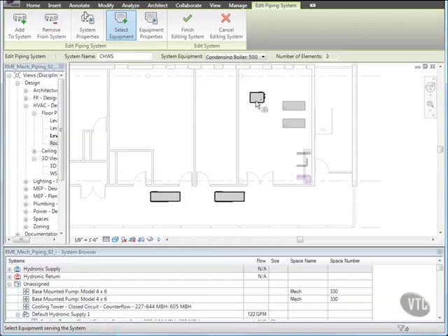You're selecting the boiler as equipment for supply to the heat pumps. The boiler is the only equipment that has connectors with compatible system types, hydronic supply and hydronic return. In heating mode, the boiler supplies heated water to the system and bypasses the cooling tower. In cooling mode, the cooling tower provides cooled water to the system. The water returns through the boiler into the cooling tower by way of the heat pumps.